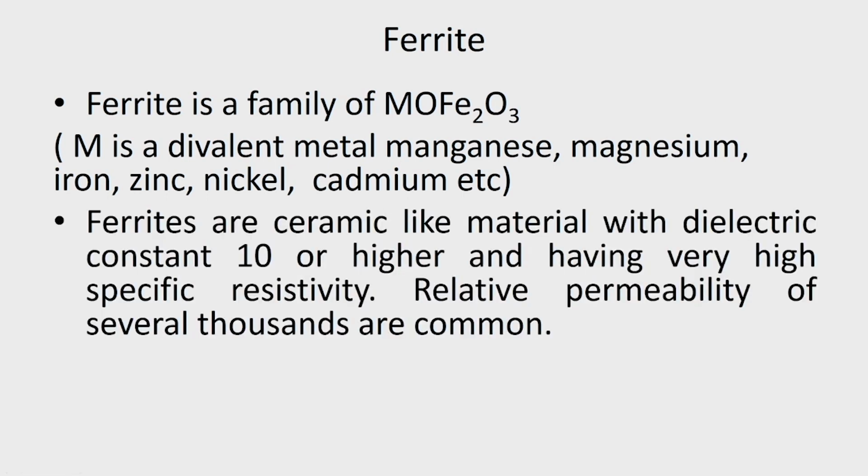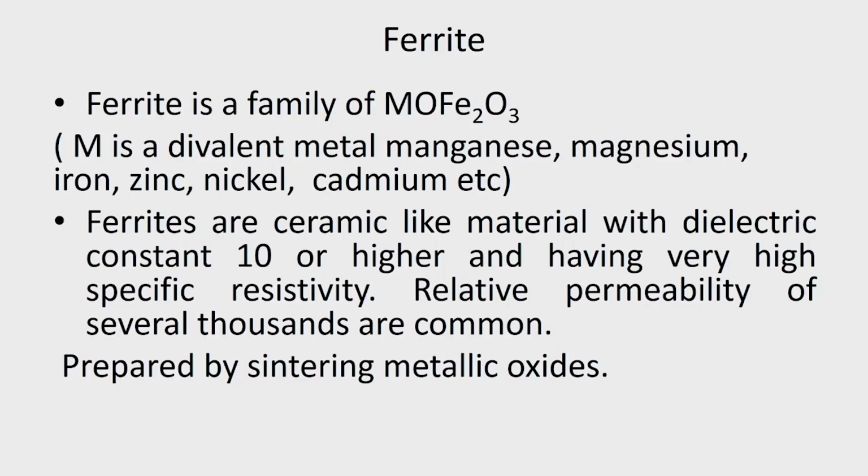Now, these ferrites are ceramic like material with dielectric constant usually 10 or higher, and having very high specific resistivity and relative permeability of several thousands are very common for this type of material. Now, they are prepared by sintering metallic oxides.